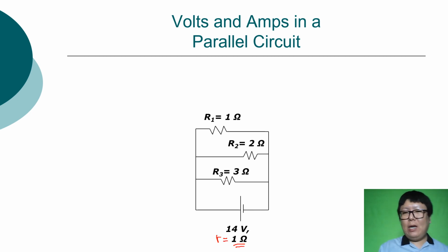If there is a resistance beside the voltage, it means that there is an internal resistance. So 14 is the EMF. To count the current, you have to use the EMF. Then what should you do for the first time? You have to count the RT first. There's no other way. You have to count the RT. Then you get the I total.